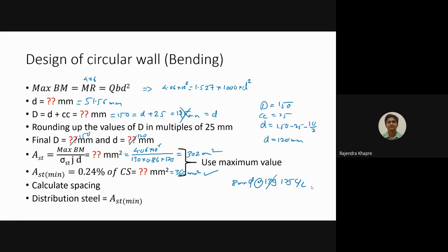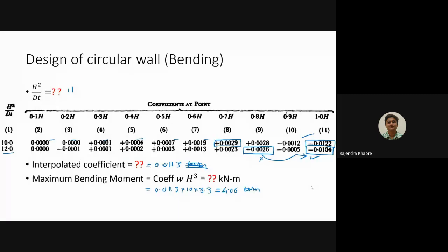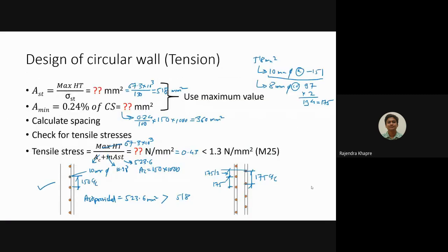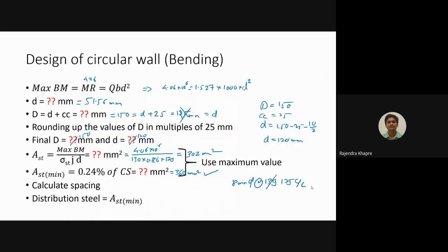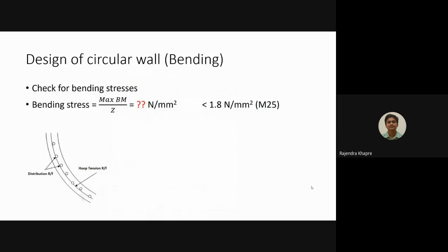Okay? So remember, we have finalized the drawing, the one on the left hand side. We have provided the reinforcement only on one side, so definitely we have to provide the vertical reinforcement on one side only. In this figure, the vertical reinforcement will be shown as circular dots.